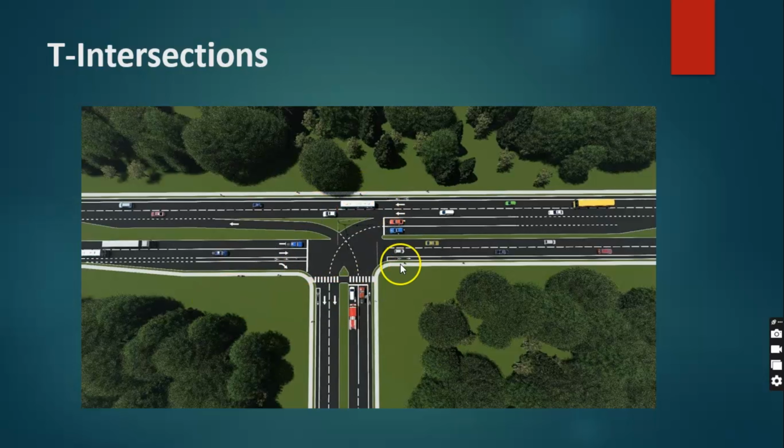So it's all dependent on the traffic flow in this area that will determine if it's going to be signalized or unsignalized. I explained that also earlier. When it is signalized, that means there's going to be the presence of a traffic light, and that comes with a high volume on the road. But if it is unsignalized, that means there's going to be the use of yield signs and stop signs, and that also is dependent on the level of traffic volume on that particular road. So this is what we call a T intersection.